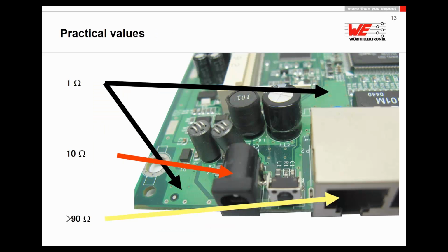Let me see like that. A power supply, VCC, has a system impedance of roughly 10 ohm, very, very rarely 20. If you're working on data lines, the noise on the data lines can see more like 50, even higher, like 90 ohm system impedance. If you want to filter ground planes, because you are splitting digital ground from analog ground and you put these ground points together, well, the ground to ground connection system impedance will be less than 1 ohm. Don't try to use a ground plane which has more like 1 ohm. Normally milliohm is much more welcome.